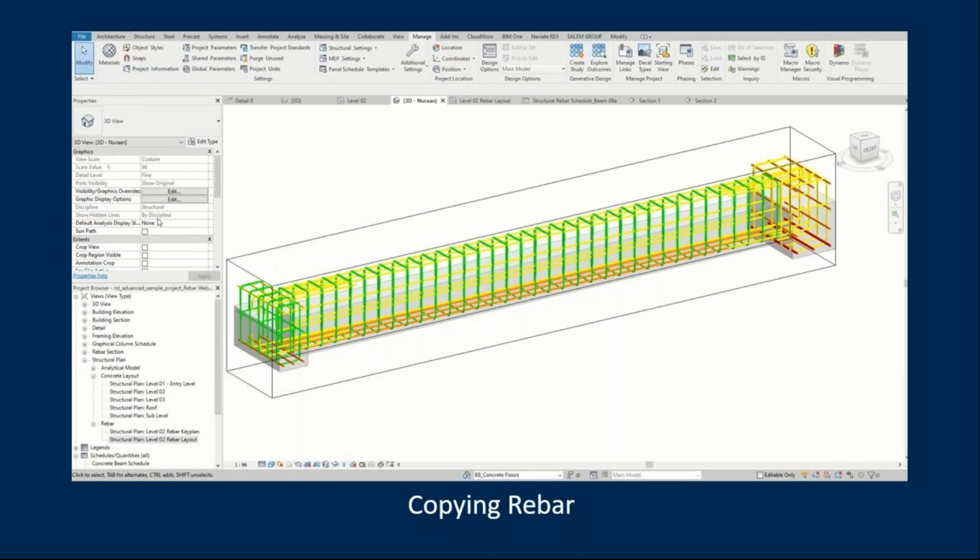Prior to 2020, copying wasn't always very seamless. If there's anybody on here who has used Rebar in Revit before 2020, I'm sure you'll agree. But there has been a lot of improvement to the copy logic. There are also a few add-ins that you can use to make copying the rebar easier than the native tools in Revit. But what I particularly like is creating groups of rebar and then copying that group to whatever identical element there is that shares the same rebar.